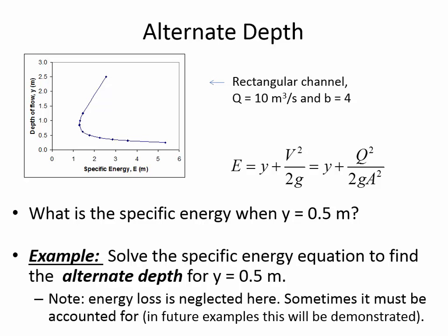And we're going to use calculations of specific energy to help us understand how the water is going to react to non-uniform conditions. The other key is whether conditions are supercritical or subcritical, because whether it gets deeper or shallower in large part is dictated by whether it's supercritical or subcritical. And we'll get into all of that, but I just wanted to give you a glimpse of why the specific energy calculation is so important and why it's important for you to be able to generate a specific energy diagram.